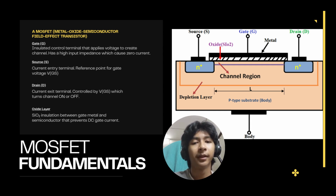So you may be wondering, if you're not allowing current to flow, then how exactly is this thing going to connect? Well, let me introduce the concept of electrostatics. You see, even though the current is not flowing here, when there is electricity at the gate, at the oxide layer, it will produce an electrostatic force that will cause a static charge all over this plate.